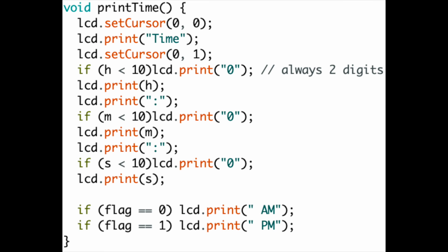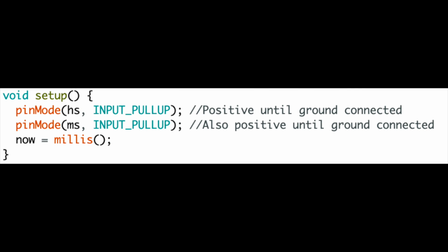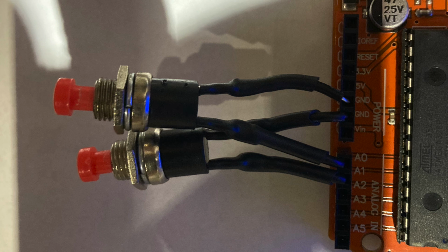The use of this code saves the time and space from the use of hardware materials which would otherwise complete the functions. The primary example being the real-time clock IC, but also in the way that the buttons are connected to the Arduino by implementing them as input pull-ups. This saves the hardware struggle of having to maintain a high signal and a low signal on each end of the button while not in use.